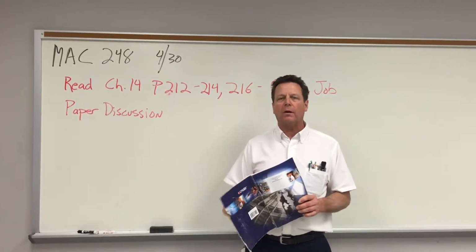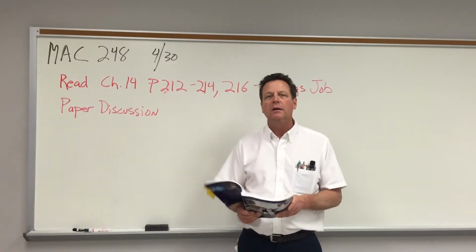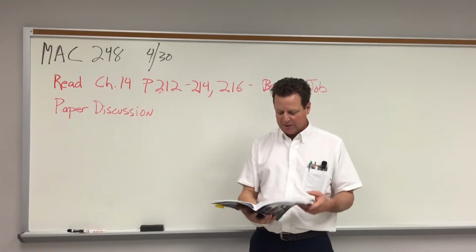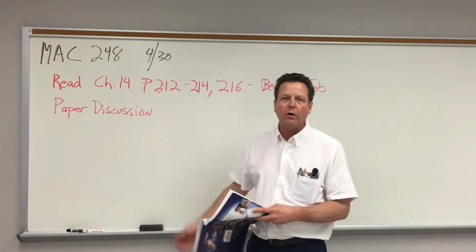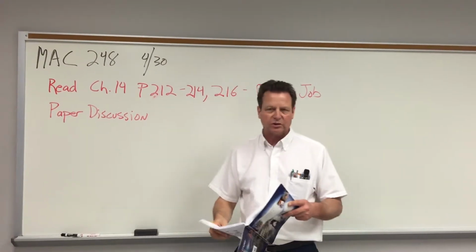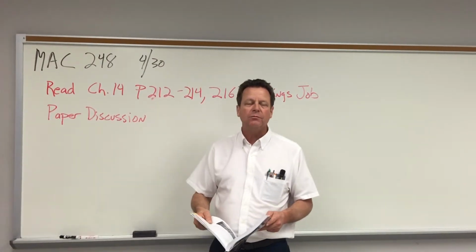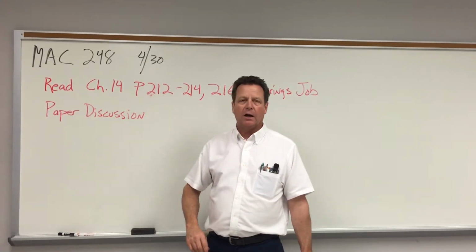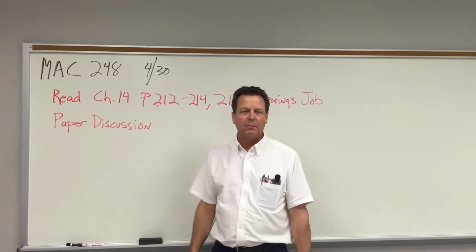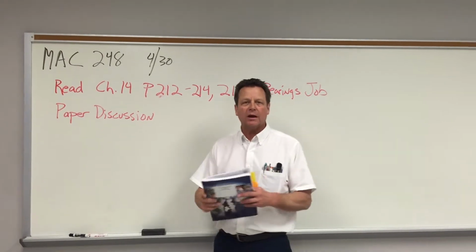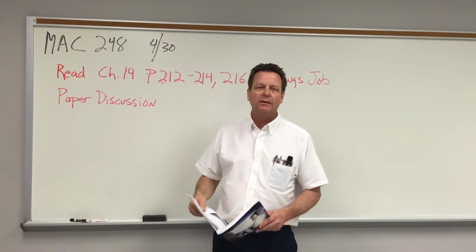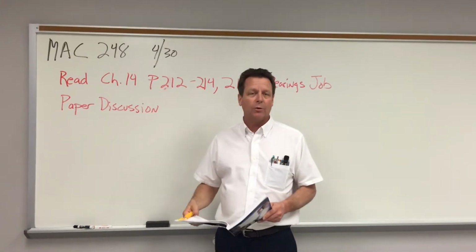Rather than checking every single part, which would be prohibitively expensive anyway, we can check every 5th part and ensure that we are within process specifications. So there are 2 causes that we have to look out for. Common cause variation, or just common variation, is something you really can do nothing about. It's like if you're making hamburgers one after the other, and the pickle's out on the edge of the hamburger as opposed to right in the middle of it. No big deal. The customer's not going to be mad because the pickle's off center. So you live with that. You expect it. It's assumed, so it's no big deal.